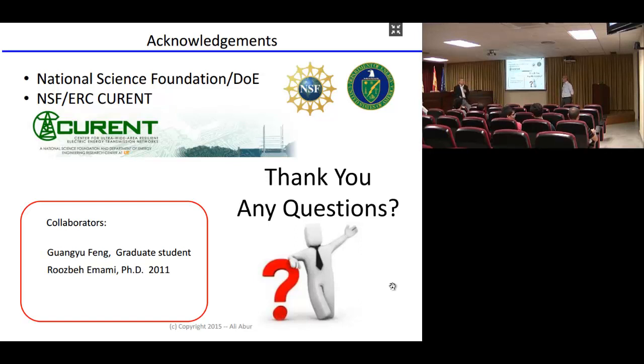Okay, yeah. My question was because what I find really useful and interesting is the distribution case, because in the transmission system, as you know, they have these digital relays, IEDs. Yes. And for those digital relays, for instance, Red Eléctrica is adding PMUs just for relaying purposes, not for state estimation. So those IEDs can be immediately connected and can report the trigger of the line immediately to the control center. So they could do basically the same. So in the transmission system, there are other sources of information, mainly the protection system. Right. So they can give you this information readily, almost real time, without alarm, and give you an estimation of the distance, because they are distance relays. But the real challenge is to have the same luxury of information in the distribution system.